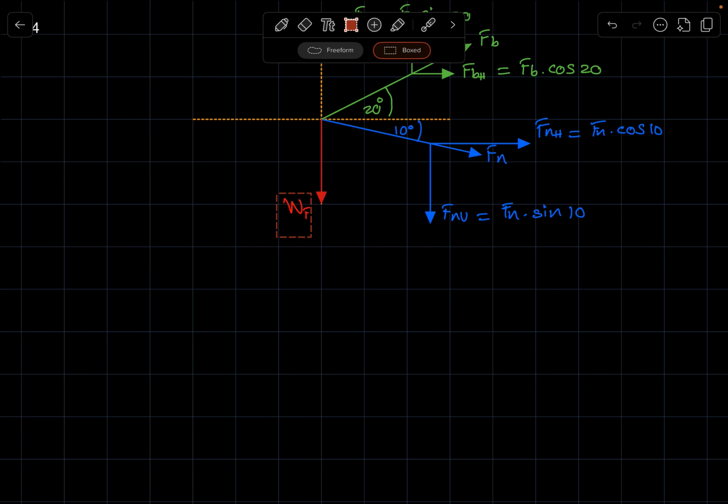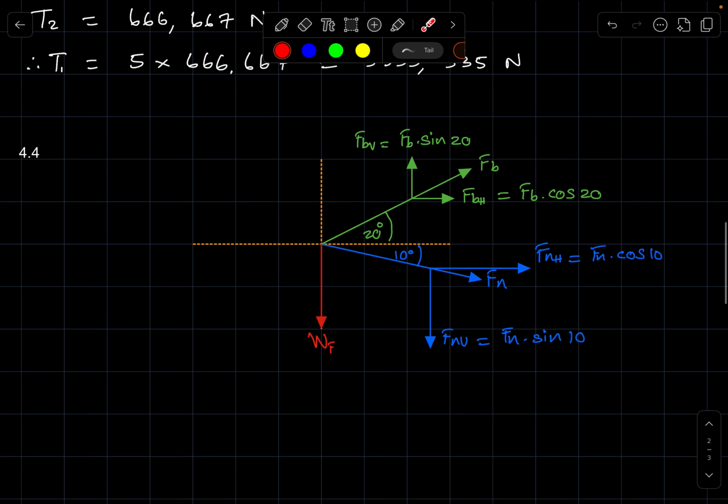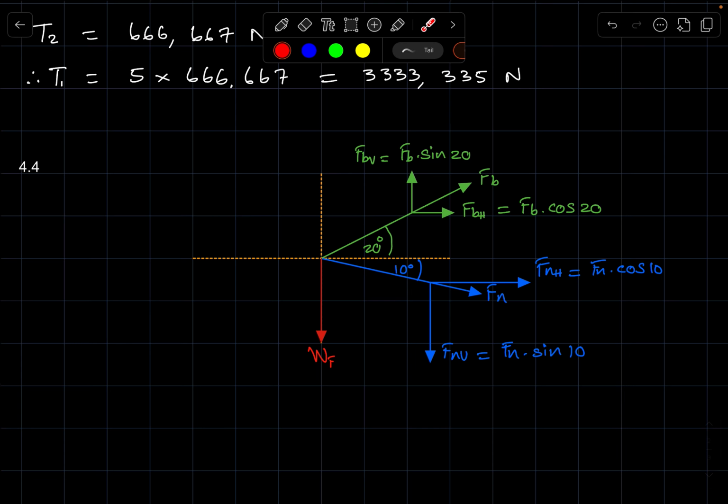So this represents the weight of the flywheel. So as far as the Cartesian plane of the line shaft, these are the forces that we are going to get on it. Right? Having established that, now we can calculate the belt force as well as its components, and then we've already calculated the normal force, so we just need to calculate the components of the normal force.